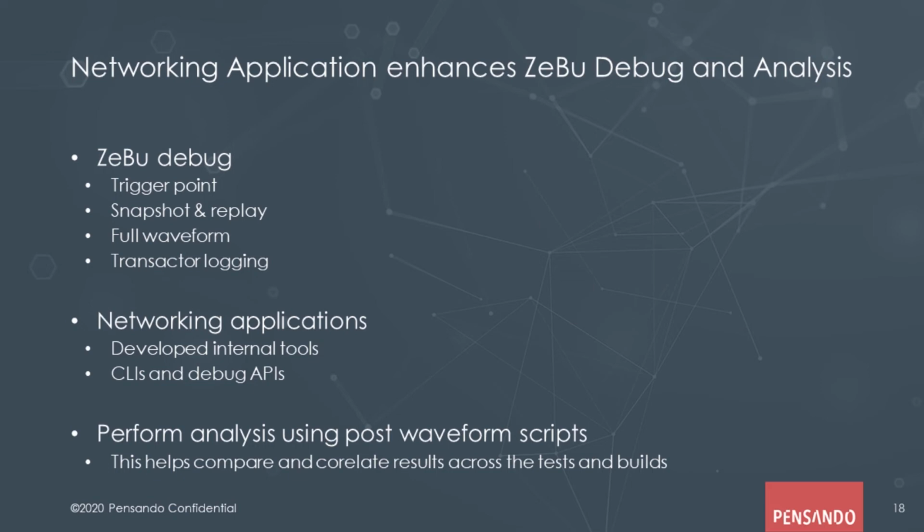By doing that, the advantage is that you may run 1 or 2 billion cycles, but then let's say you find that this error condition has already triggered, then you can go back every half hour to find the exact window you need. Now, when you know the window, you just replay that part and not the entire billion cycles. That gives us a lot of advantage in replaying and running more cycles, because we know that whenever anything fails, we can definitely go back and find our error window.